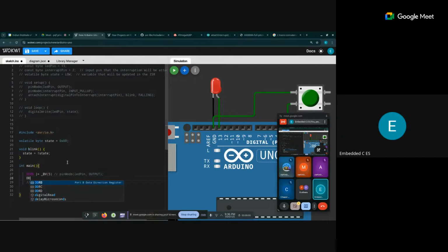First we'll set up D2, right? So we will explicitly set this to low. Yeah, I'm resetting that pin, and also I have to do port B. I have to do a pull up part, right? This is basically setting to the input mode, and this is the pull up part. For pull up, we have to set it to 1.